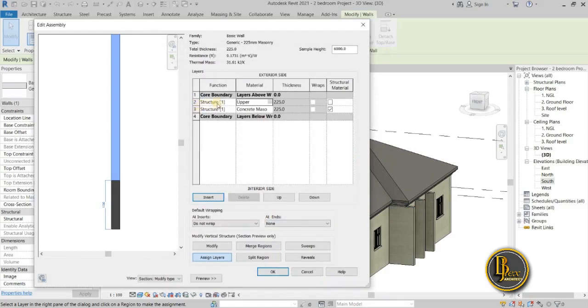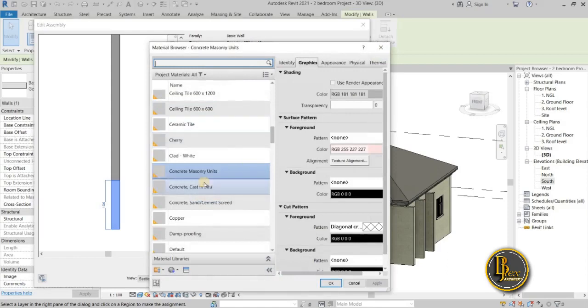You can see the structure at this point. You see it's assigned to upper. This upper one has a new color, which is that peach color, but this lower one has no color yet. So you just come here, click on this. Now what you're seeing is that lower one. Now let's go to the Masonry block. It's that concrete masonry. So you can duplicate this.